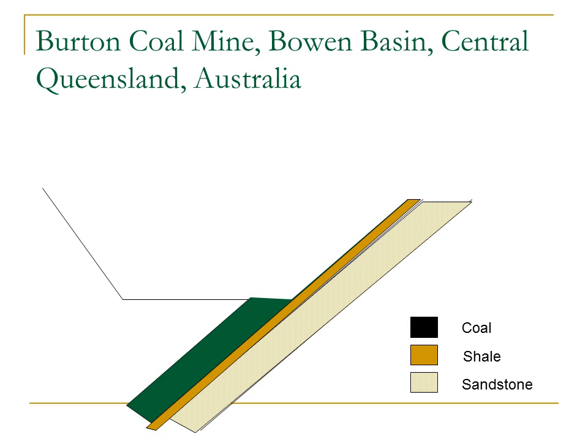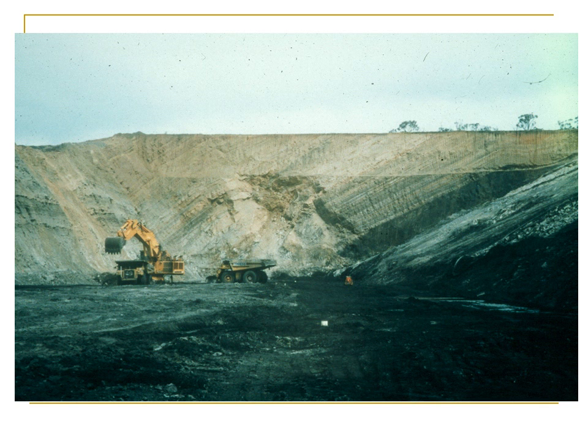That decreased the effective stress acting on the base of the shale layer, and eventually led to instability of that shale layer. I've got some pictures of it next, but they're very hard to view because they involve the trace of the coal seam that had been mostly removed at that point, and coal does not photograph at all well. So here's that, you can see the coal seam in the high wall of the mine. So there's the coal seam that they removed over most of the mined material in the foreground.